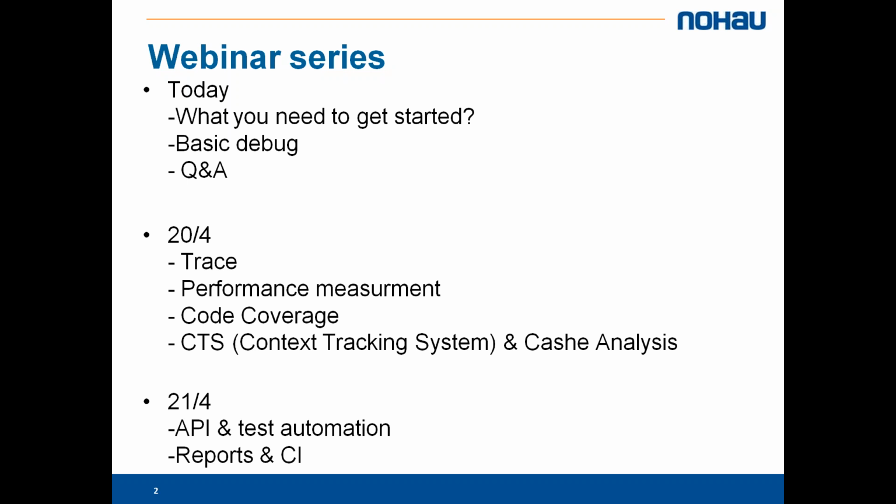Tomorrow, at the same time, I will show you what you can do with trace, either if you have an embedded trace buffer on your target, or if you have external trace hardware from Lauterbach. What type of performance measurement can you get? Code coverage, and also what reports you can get with code coverage. I will show you cache analysis and also what you can do with the context tracking system.